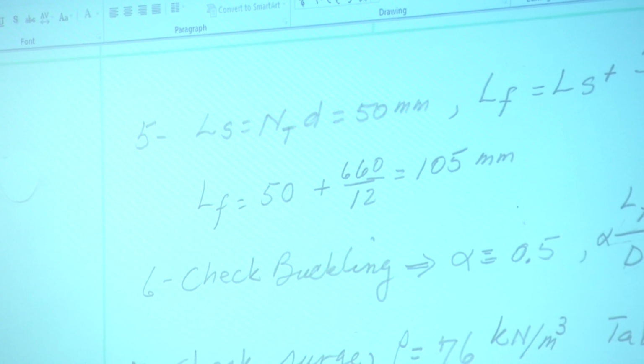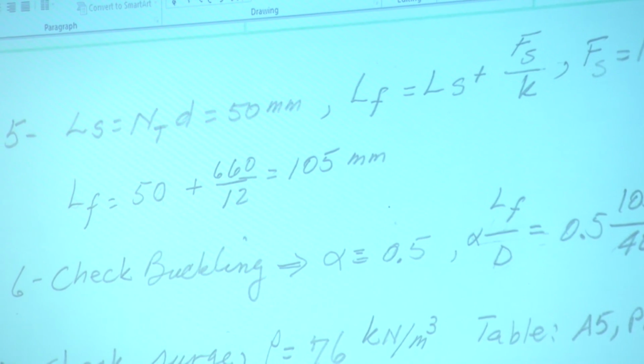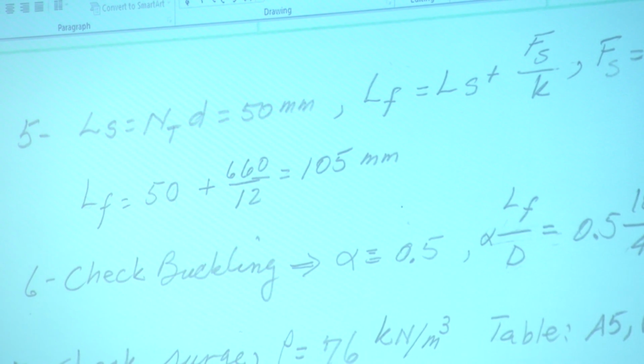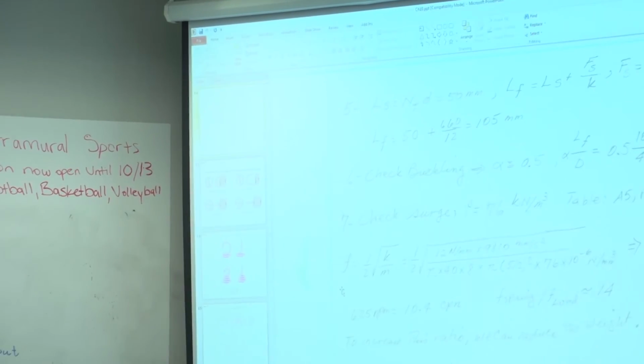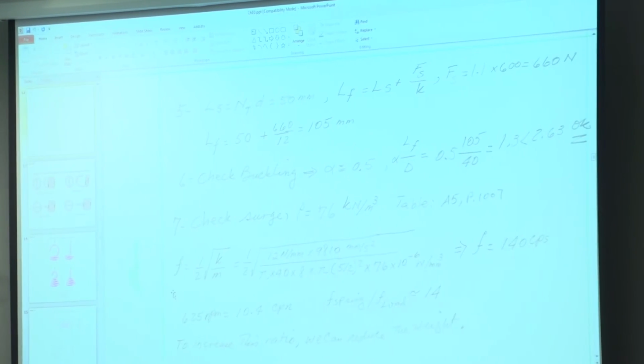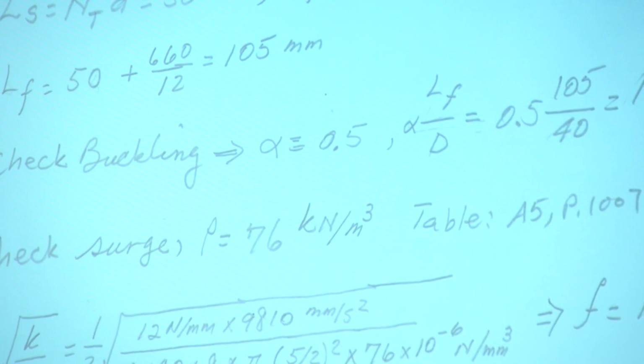Now the question is, if I want to find the deflection at solid length, and I have K, which is the spring constant, I need to know what force should produce the solid length so that I can find the deflection by dividing that force by the spring constant. We get that force from this consideration.